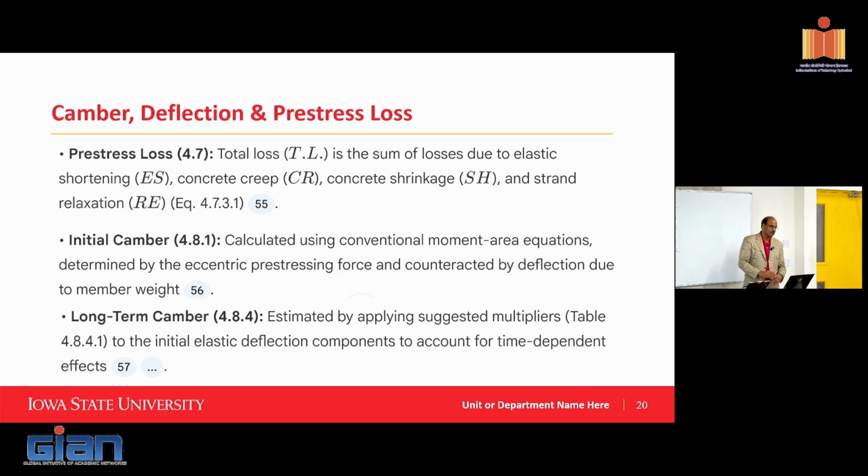So ideally, the best scenario for a prestressed concrete structure, when you're using floor slabs or beams, is to allow the camber to happen during casting. By the time service load goes in, it's going to settle, right? For gravity load, the service load is going to go down because of the deflection. So if I'm starting with an upward deflection, the ideal position would be to eliminate that camber and become a flat section, right? What's the advantage of keeping it flat?